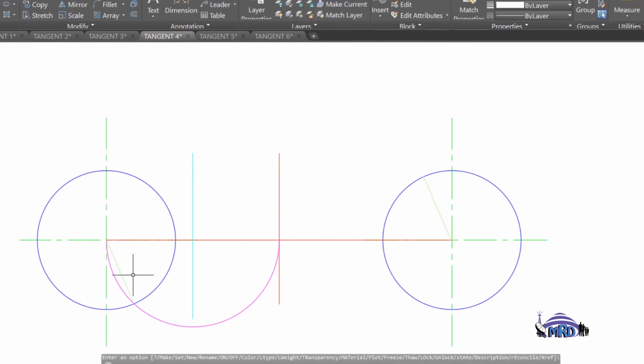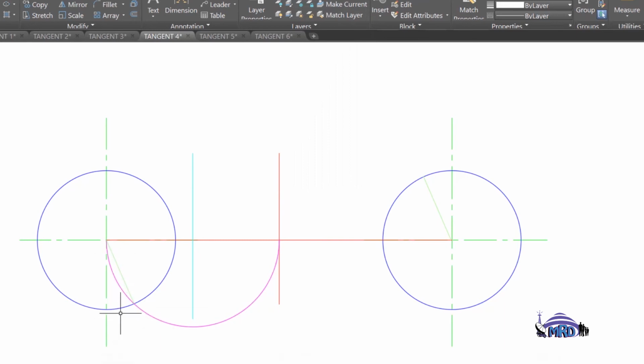And this normal here then would be locating the tangent. Now, because it's an internal tangent, you would need to produce a normal on the opposite side. If you were using the drawing instruments, you would be taking your set squares and you'd be sliding to get the parallel line up the other side. Here you can take the line and transfer it over to the other circle. A variety of ways you can copy. You can take the angle and move the angle over, but you would produce a line parallel on the second circle on the opposite side to allow you then to locate the tangent.